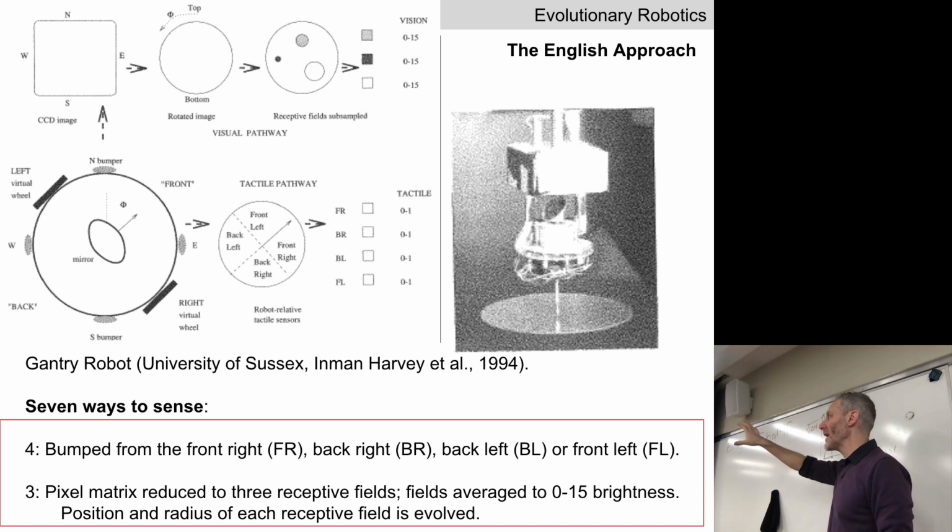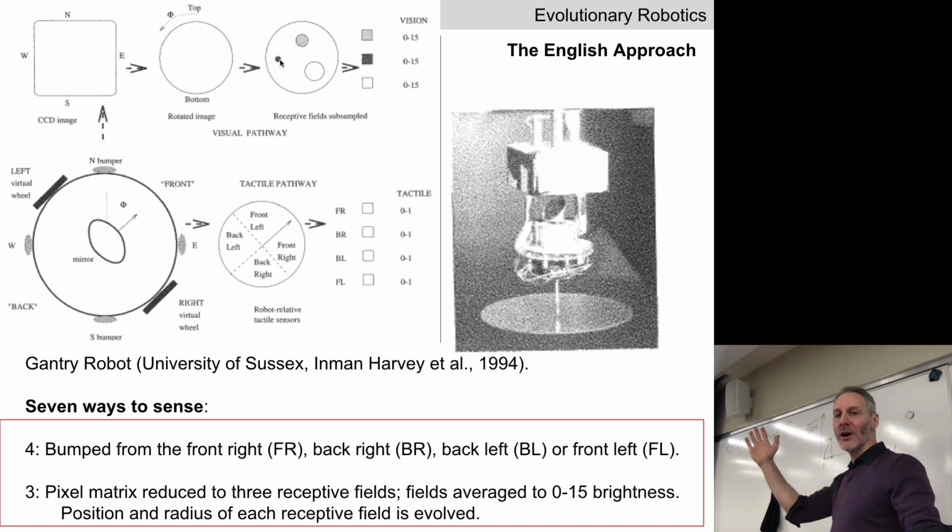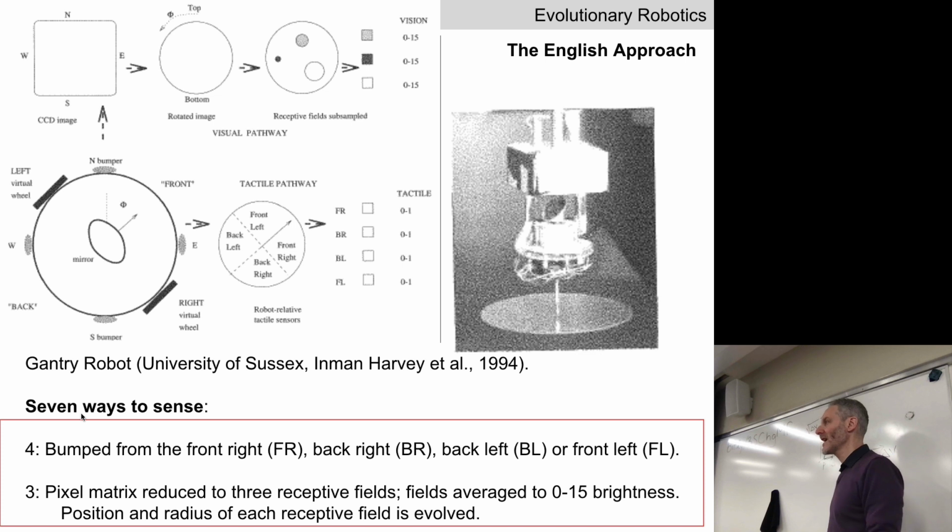So they're also throwing away color, they're throwing away detail, shape, lines, cross-hatching, all the other detail that might have been captured by these pixels, and reducing everything that's inside that single fovea to a single number. What's the average brightness of the pixels inside that fovea? So far, so good? Okay, so for a given snapshot from the camera, they're going to get back 3 numbers from these 3 fovea, the average brightness inside of these 3 fovea. Those are sensors 5, 6, and 7.